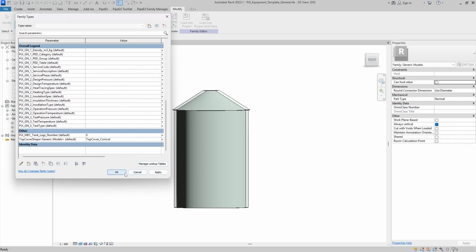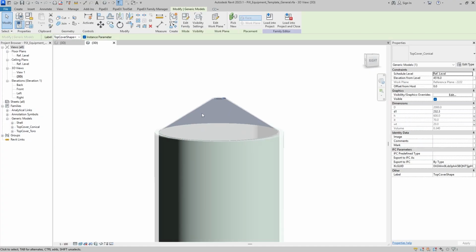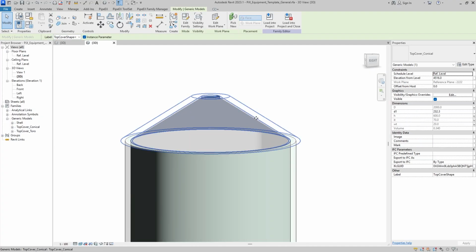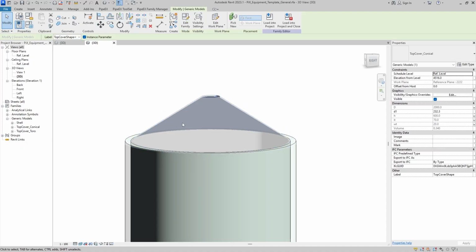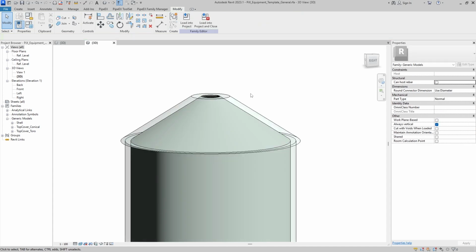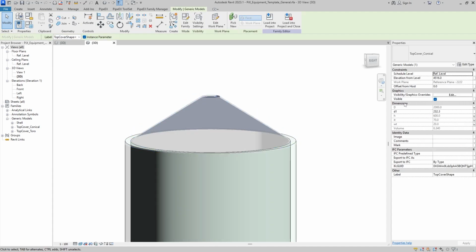Now I'm going to show you one thing that I mentioned before, why you need to ensure that you always have the maximum number of parameters. So if you would like to ensure that the families are exchanged or swapped in places in a proper way, and you don't need to always modify anything, you need to ensure first that every family that you're going to exchange in places has the same number of parameters.